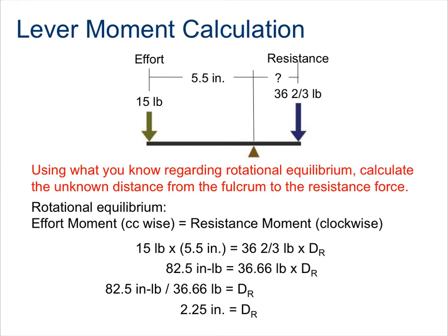Using what you know about rotational equilibrium, now you should be able to calculate the unknown distance from the fulcrum to the resistance force. So again, to consider rotational equilibrium or static equilibrium, our effort moments going counterclockwise have to be equivalent to any resistance moments going clockwise. So in this scenario, my effort force is 15 pounds. My effort distance is 5.5 inches.